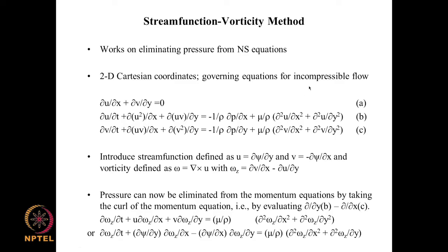Since we are looking at incompressible constant property flow, the second coefficient of viscosity term does not appear. It is usually something plus λ times ∂u_k/∂x_k, and ∂u_k/∂x_k equal to 0 here. So, the second coefficient term goes to 0, and this is the equation here. Since we are looking at constant property, constant density flow, gravity does not come into the picture. It has no way of influencing the velocity field. So, we can subsume it in the pressure here, or we can simply neglect it.